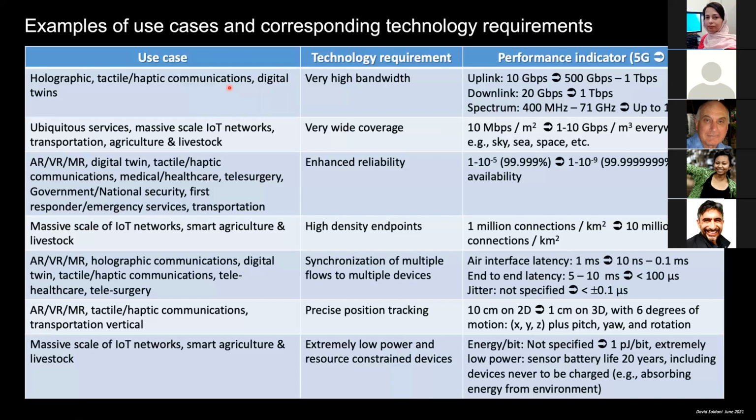But more importantly, I think, is the way we need to connect the intelligence. AI is the most important enabling technology, driving the research and later the development of next generations of mobile communication systems. If you look at the corresponding requirements, we didn't have strict requirements of energy per bit for 5G, and we didn't place requirements on jitter, which is now expected to be there. Speeds, yes, as I said, we're expecting at least 10 times more. We are thinking of even up to a terabit per second. The spectrum is a key element that is expected, at the moment, to go up to 10 terahertz.